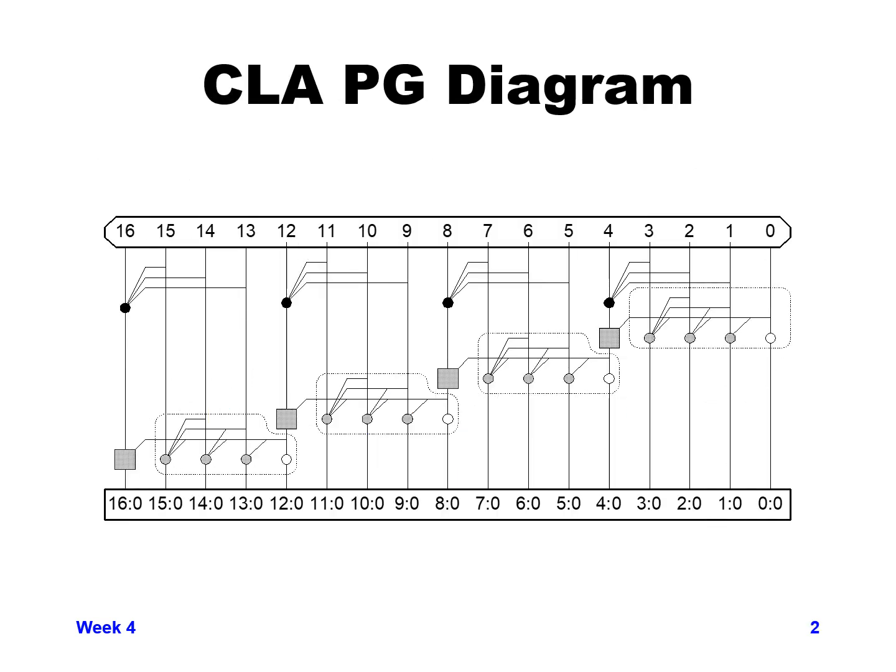Now let's look at the delay diagram that we could get for a carry look ahead adder that we were talking about using in the previous foil. In this case, using carry look ahead, instead of propagating a carry through 4 stages, we'll design a really complex single stage to do the same function in a single stage instead of waiting for 4 stages worth of logic. These single stages of carry look ahead are denoted by the circles as opposed to the squares.